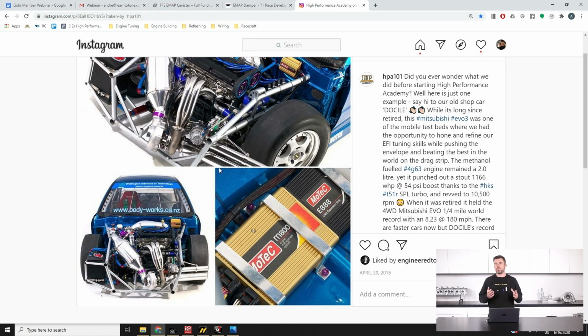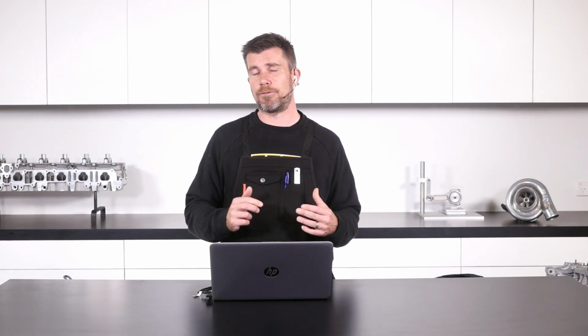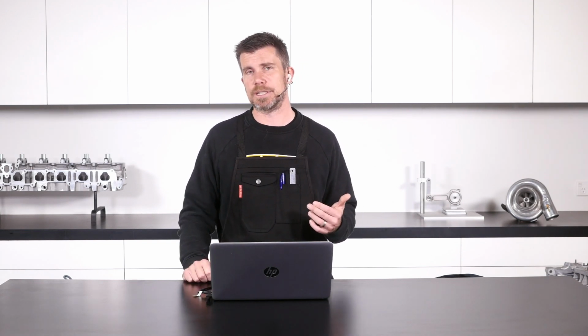There's no real golden number that you must have. The ratio between EMAP and IMAP is going to be very much a factor of the type of motorsport that you're using. And obviously, if you were going for very low EMAPs like we were for drag racing, the turbocharger would be completely useless for anything else, particularly road use or even road racing. So it's very much deciding on what your purposes are before you start chasing down a specific number.